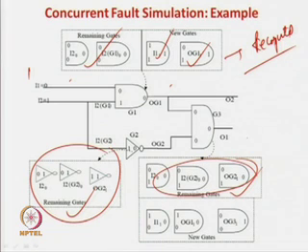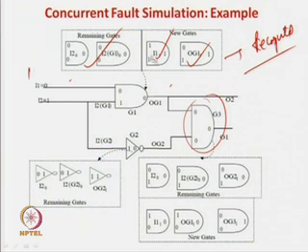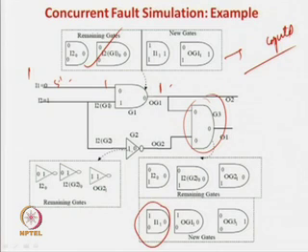Similarly, for this gate if you check, some new gates will be added. So, what is the new gate that is added? Now obviously you can see that this was a stuck at 1 fault here, this is actually 1, stuck at 1 fault over here. If we stuck at 1 fault, then the answer is a 1 over here. So, there will be a signal change here, and this gate will be added by this one. So, stuck at 1 here means the answer is a 1 over here. Instead of 0 the answer will be 1 1 1 0.